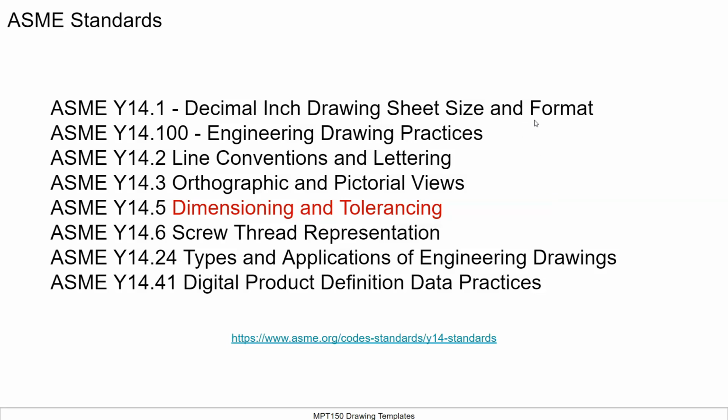All right, so the ASME standards. Y14.1 is your decimal inch drawing sheet size. There are ones that have an M, that would be the metric. 14.100 is the engineering drawing practices. 14.2, line conventions and lettering. Orthographic and pictorial views, 14.3. Not sure if it was the 14.41 that jumped it over, but pretty much the main one that we'll be working with is 14.5,